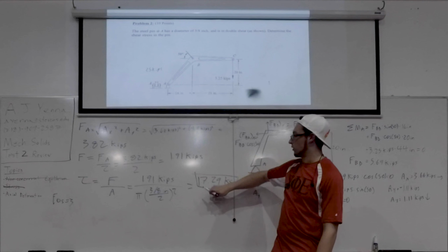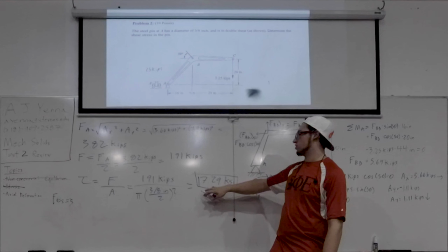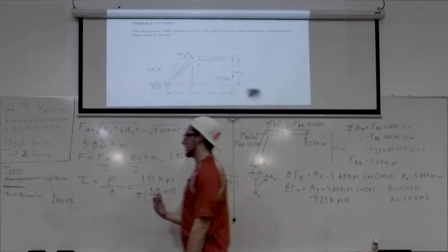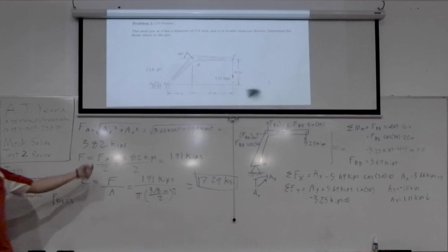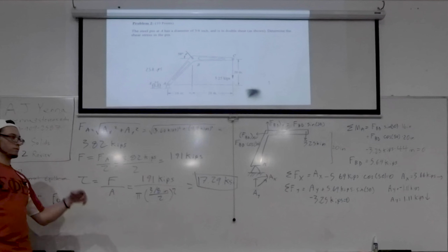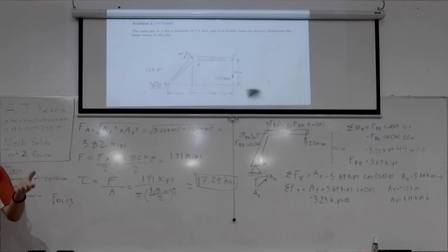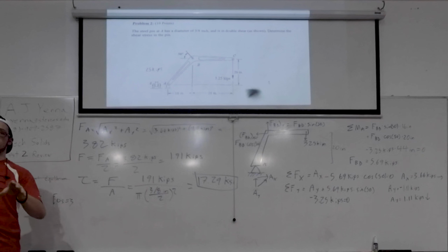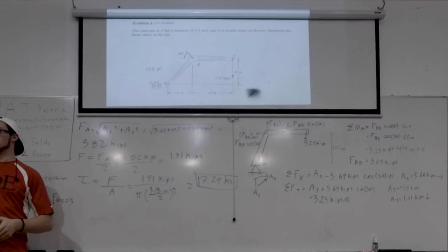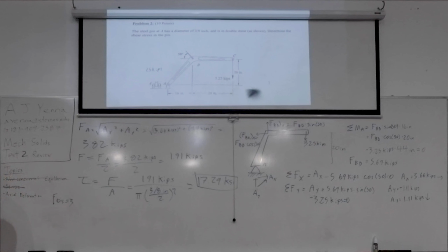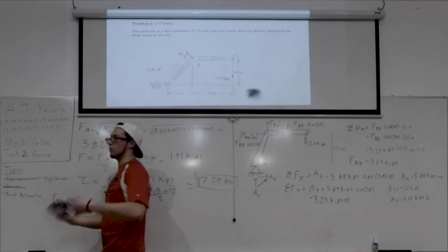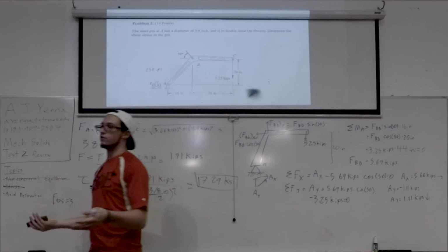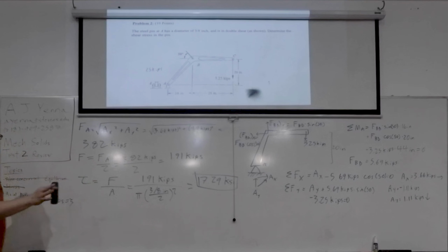This 1.91 kips will essentially break the pin if this is your maximum. So you kind of have to back design it, but just remember that this factor of safety will decrease the force. Are there any questions on that? I don't think they'll give it to you, but as a little 2-point curveball he might chuck in there, it's possible. Mathematically, it's the same idea, and depending on how the question is worded, you could just do the proportion a little differently. But that's it for that.